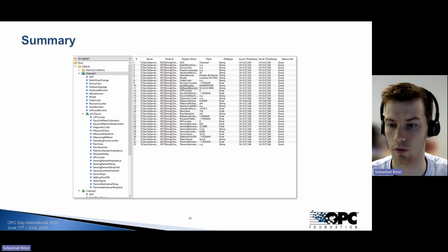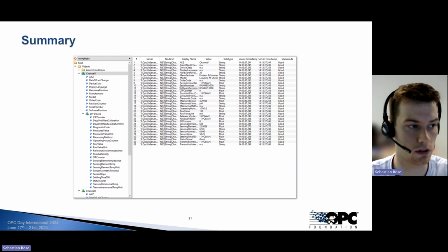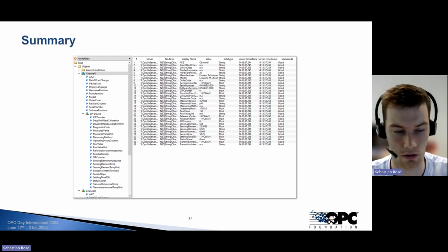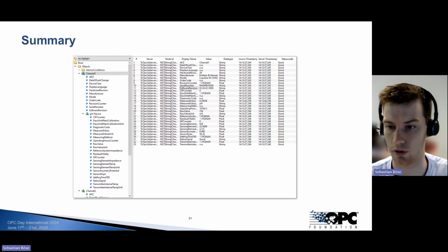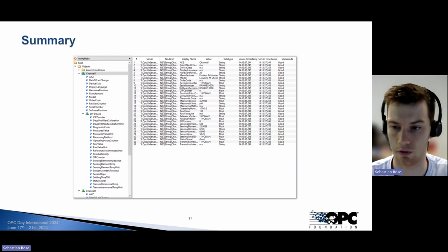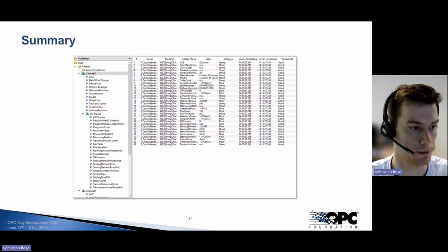We do not have any variables that aren't filled in or that aren't used in the PA-DIM, so that the end user and the customer always have the standardized information model for all the field devices that are really connected. And if there's no field device connected on channel 16 or whatever, then there's no data set in the OPC UA server. So that's the goal at the end, or that's what we achieved in the past, that we always have this completely standardized server itself with all the PA-DIM information models, to make it really easy for the customer, and that's what we did here with OPC UA.